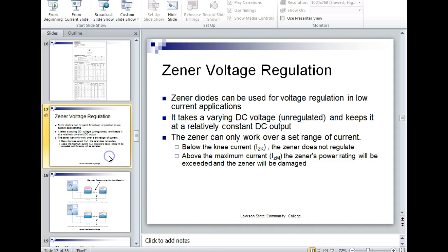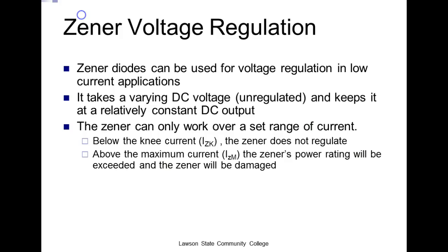So what we're saying is it's very simple to build a nice, cheap little regulator, using nothing but a Zener and a resistor and a transistor, or a Zener by itself. We'll see Zeners used all the time to change the voltage levels. So let's say I've got a device that needs to run off 5 volts, but my power supply, everything else in the system, is 12 volts. Well, all I have to do is take that 12 volts and use a 5 volt Zener to power that one device. Does that make sense?